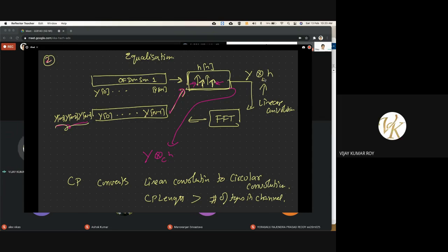It's more of a question of your SNR. The question you asked is actually a very deep question. Does it depend on your receiver sensitivity in a very non-linear manner? Yes. But generally, you don't talk about that because by the time the power will be so low that you can neglect them. If your signal is at the receiver sensitivity, you will be mostly noise limited rather than facing any of these issues. Okay.